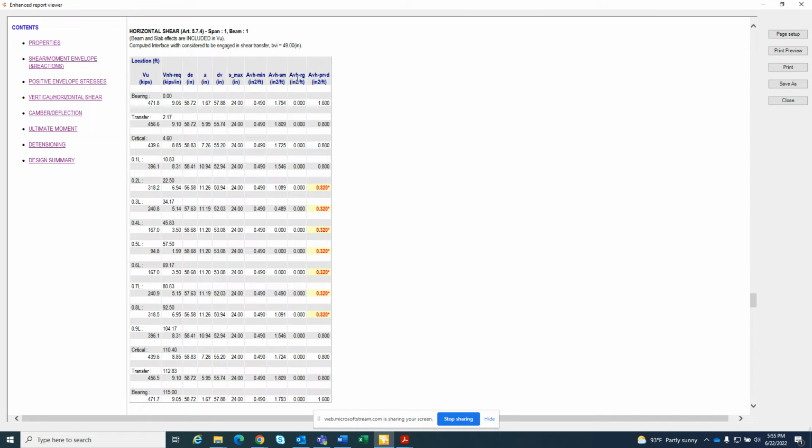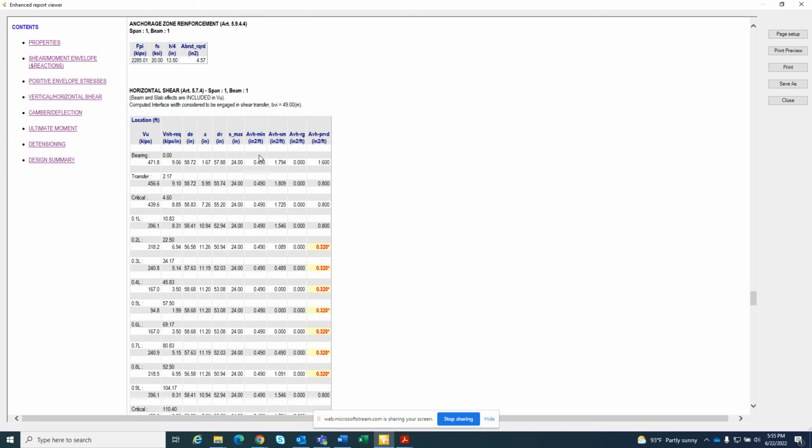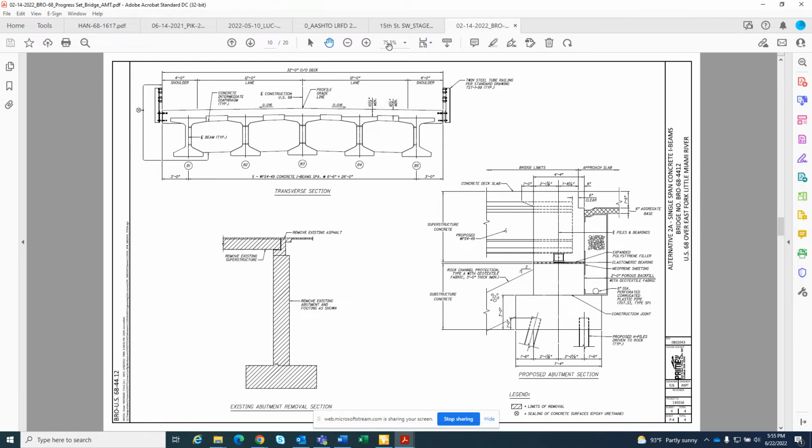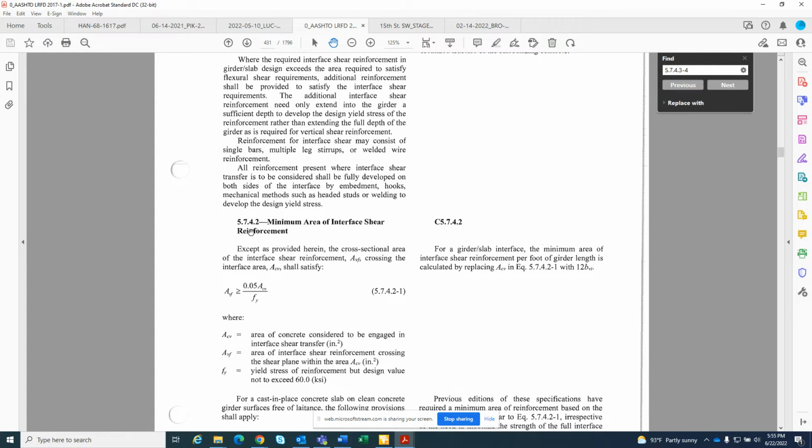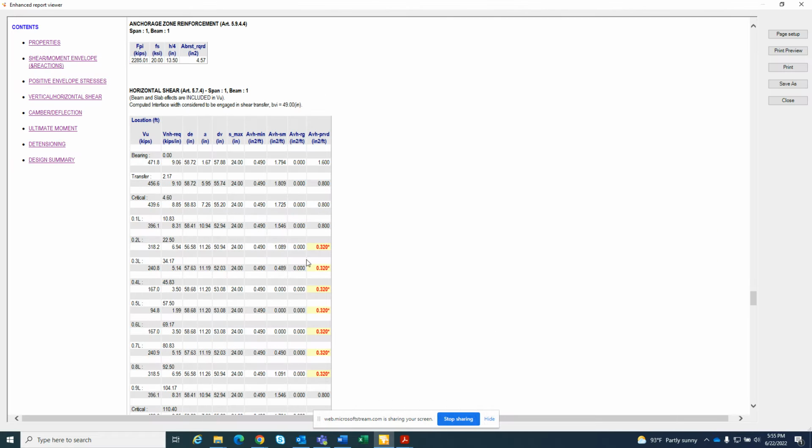Okay. For the reference surface, the software says the area of steel reinforcement required is 0. But AASHTO has some minimum requirements which is 0.49. If you go to the AASHTO article 5.7.4, that is the old one actually. So this is the actual one, 5.7.4.2. If you do this math, then you come up with the number 0.49. Okay, and then for the smooth surface 1.74.